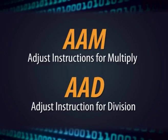The multiplication and division operations can be performed when the numbers are represented in packed BCD format. Assuming the two numbers, whether 8 bits or 16 bits, are represented in packed BCD format, when these two numbers are multiplied or divided using the mul or div instruction, the adjust instruction for multiply and the adjust instruction for division transform the result back into BCD format.